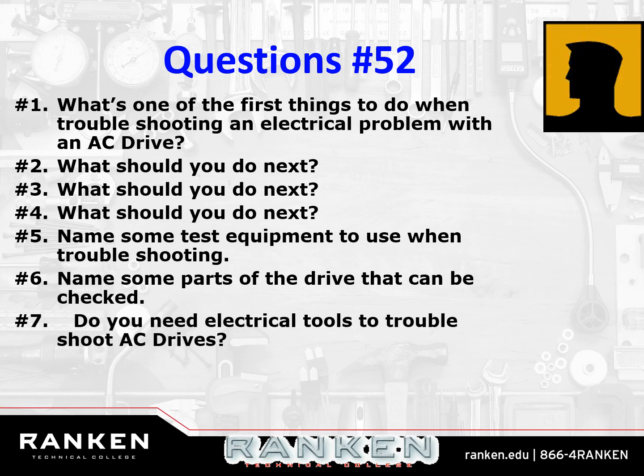Do you need electrical tools to troubleshoot AC drives? Really, you shouldn't need screwdrivers and things like that because most of the stuff is going to be accessible. You might have to have a few basic hand tools. But the biggest diagnostic tool you're going to need is your meter.